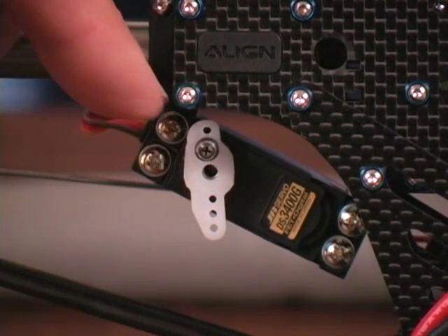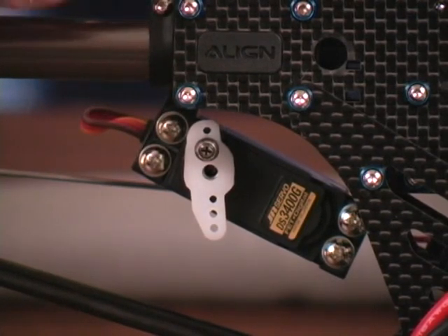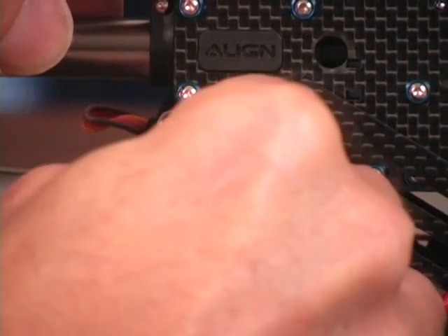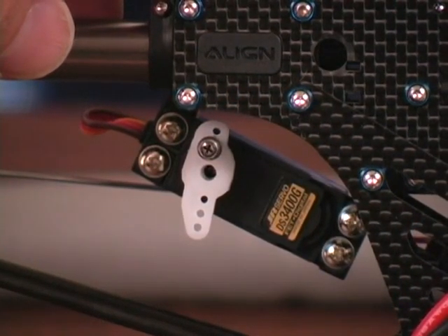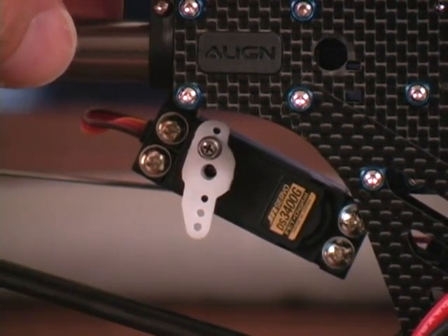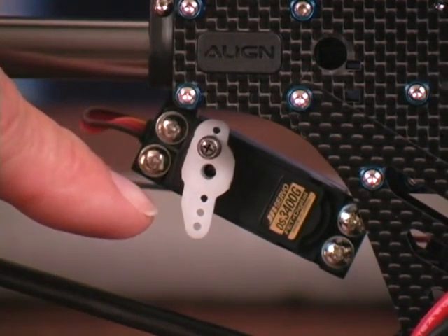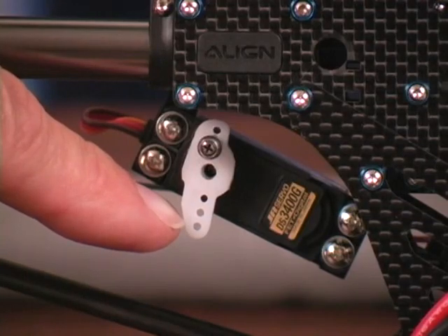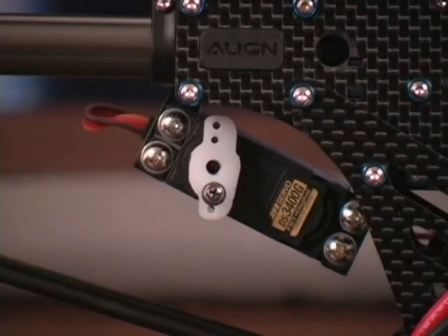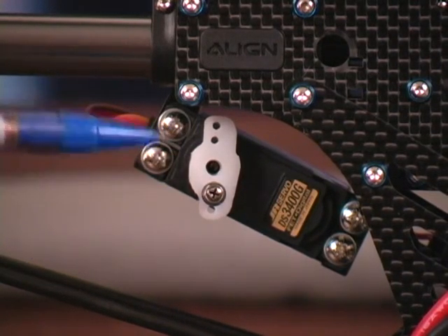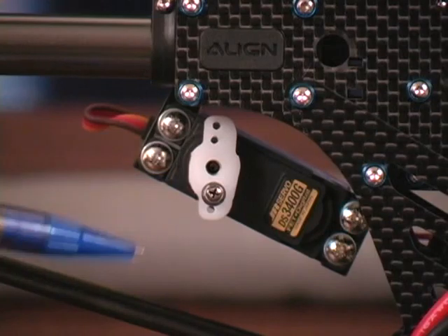Here you can see how the top of the servo arm is back a little bit too far, and if I rotate it forward 1 spline, now it's forward a little bit too far. So it looks like I'll have to rotate the servo arm 180 degrees and then whack off this excess length of servo arm right here. It looks like this is as close as I'm going to get to a perfect 90-degree angle between the push rod and the servo arm.